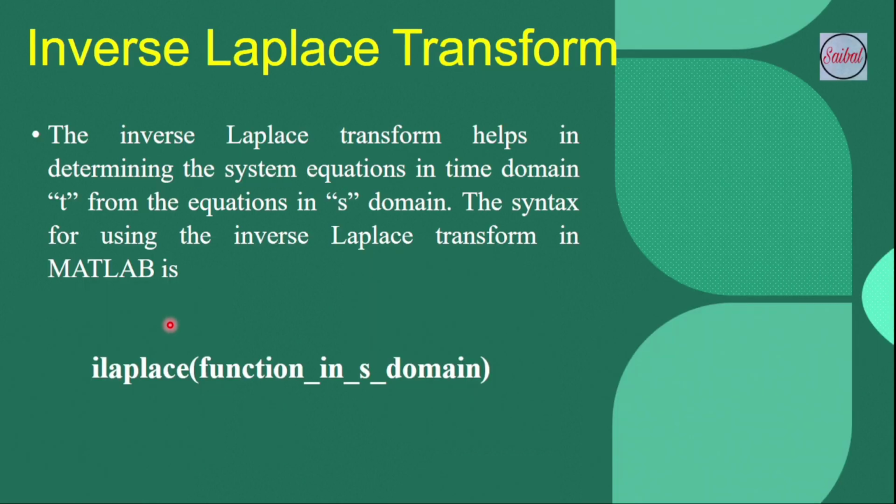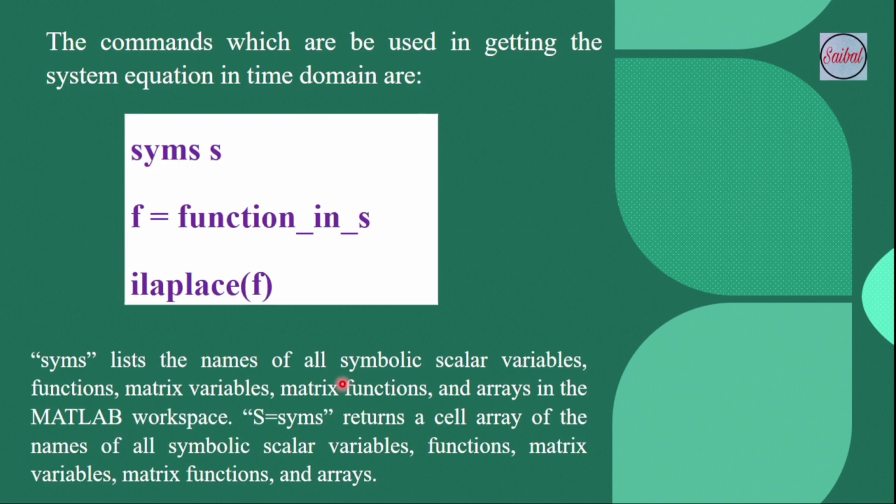So in the previous lecture we used just the laplace command to transfer the T domain to the S domain, and here for the inverse Laplace transform we use the command ilaplace. ilaplace means inverse Laplace. So in case of the Laplace we use the laplace command, and in case of the inverse Laplace we use ilaplace, and then it will be the function in the S domain.